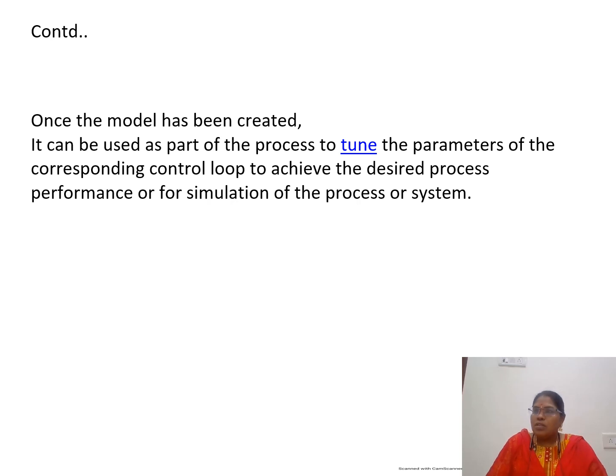Once the model is created, the next step is to use it for controller design, to tune controllers using the Ziegler-Nichols open loop method or the closed loop method, to find the performance of the simulation of any process or system.